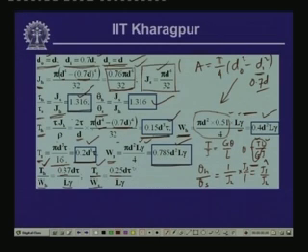Now, d tau by L gamma is constant for both the shafts, they are identical because they are subjected to the same stress for the same length, the same unit weight, and the same outer diameter. Hence, as we can see, the strength to weight ratio is more in case of the tubular section than the solid shaft.